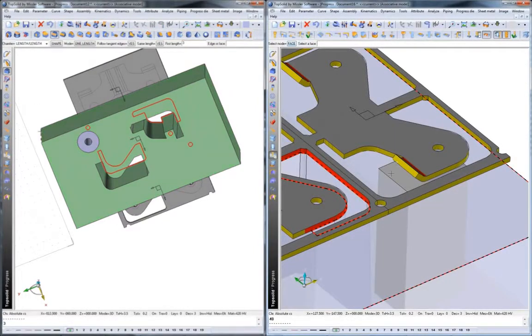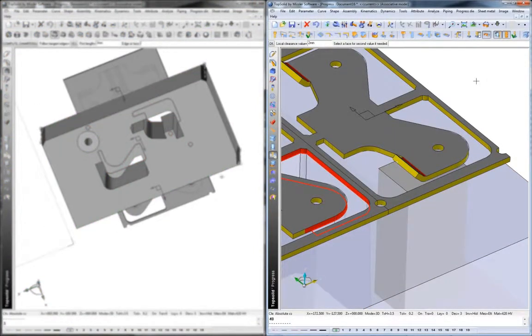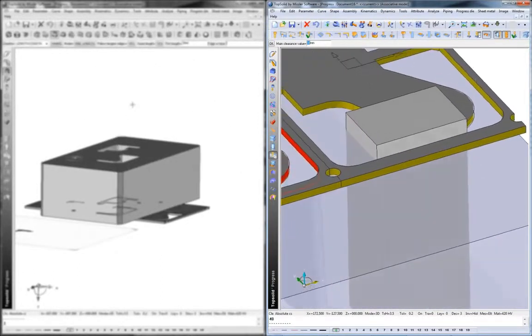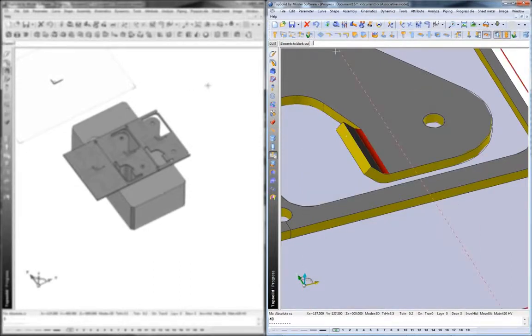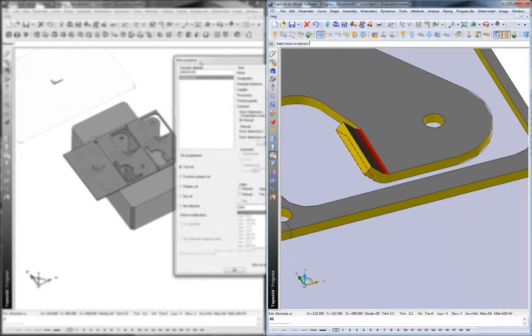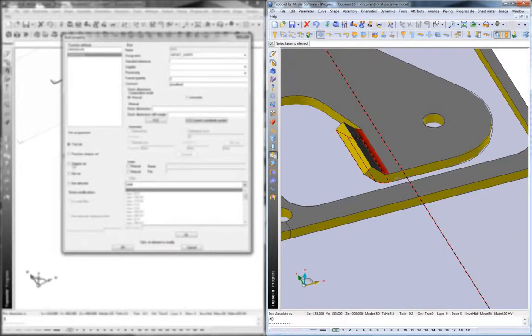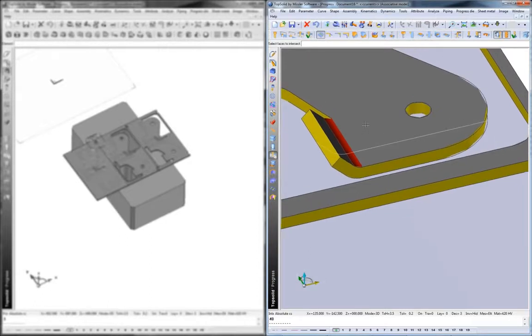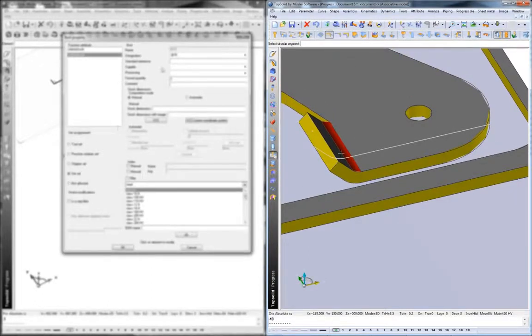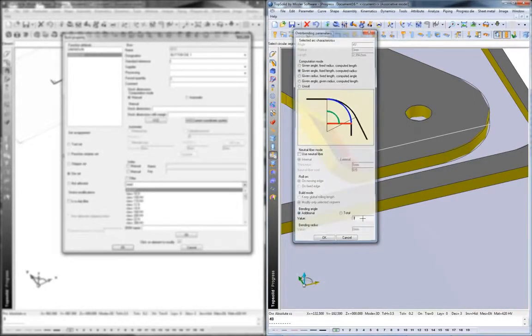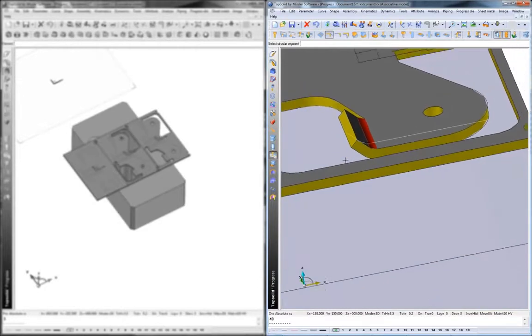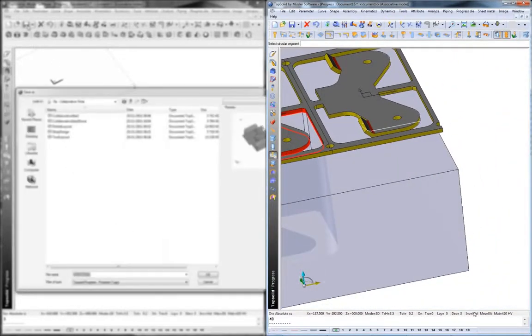Now, from here, this user is going to continue working on his project, but we're going to focus and check in on user 2. User 2 has been quietly chugging away, and he's working on the bend shapes. Let's see what he's doing. Here he's asking TopSolid to help him create the profile needed to make his bend shape. There you can see the profile has been created, and now we're going to show our die block. He's doing overbending right now. How about 3 degrees? Perfect. Then we're going to show our die block, and we're going to process that through the die block.